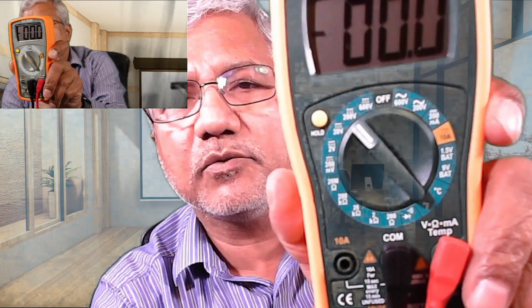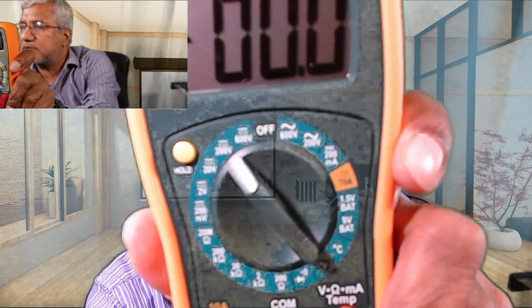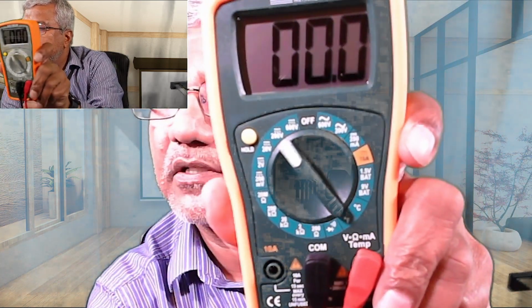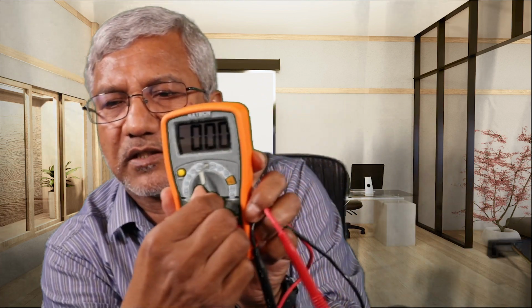And after you measure it, if you see that the voltage is like 50 volts, then for more accuracy, now we know it's less than 200, so you move it to 200 volts. So that's how you always do it. You never put it on the lowest scale. You always put it on the highest scale. And that is applicable for measurement of anything, voltages, currents, or resistances. Another very important thing is that you have to remember to turn it off after you make the measurements.